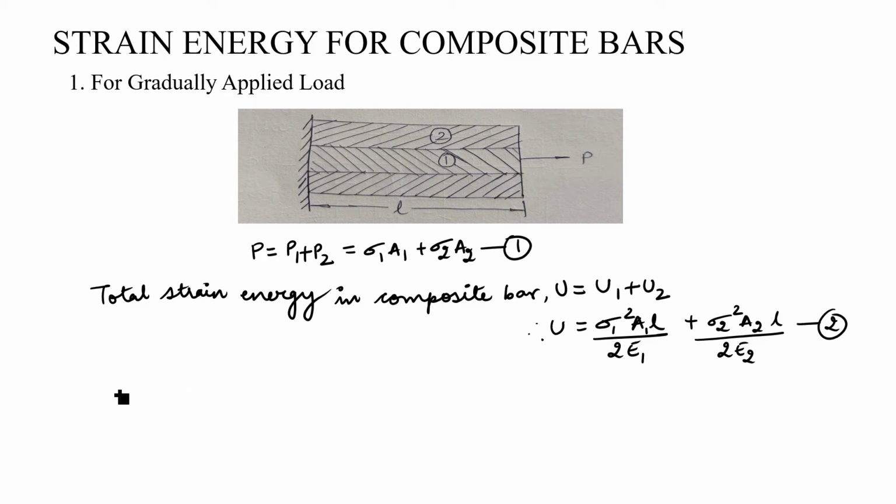Now let's talk about the change in length of each bar. If you observe carefully, this is going to remain the same because the initial length is the same for both and the load borne by them is shared. Here for the composite bar, the change in length is the same.